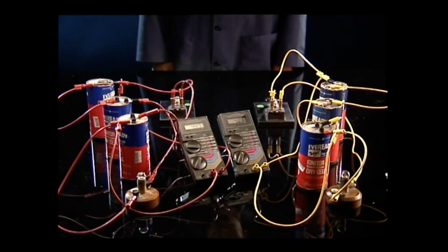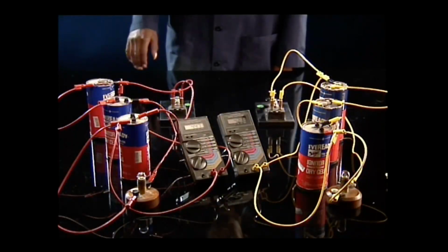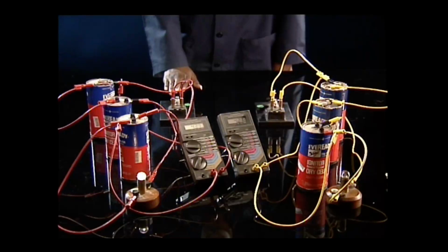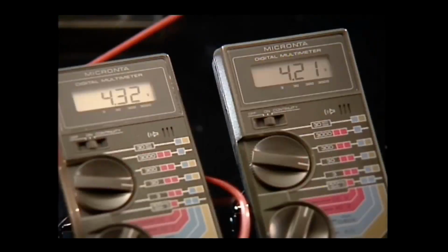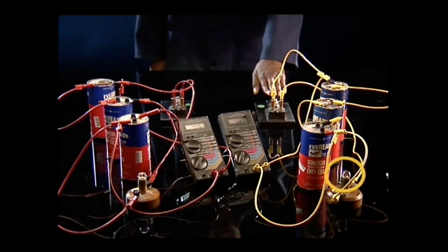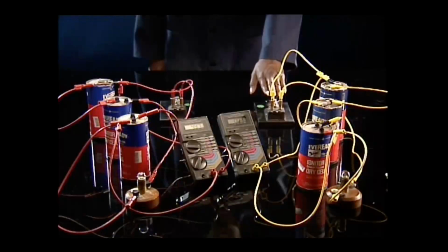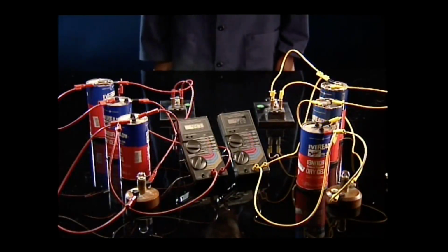These 2 sets of batteries appear identical and show approximately the same reading on a voltmeter, but there is a difference. When a light bulb is connected to this set of batteries, the bulb lights and the voltage of the batteries remains about the same. When we do the same with this set, the bulb fails to light and the voltage of the batteries drops to nearly nothing. This set of batteries has been heavily used and has a high internal resistance.